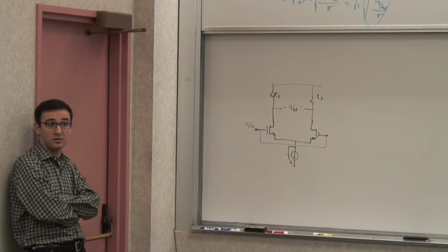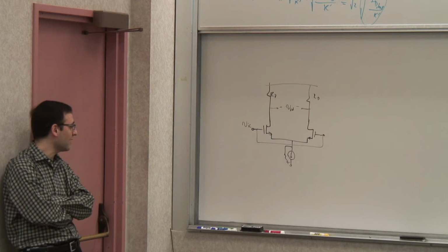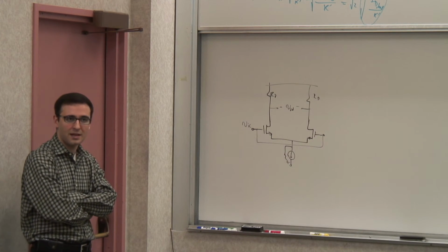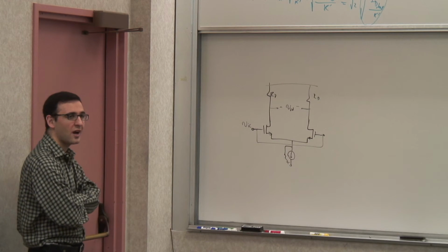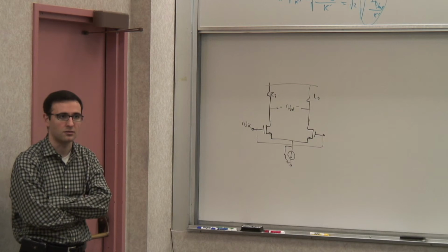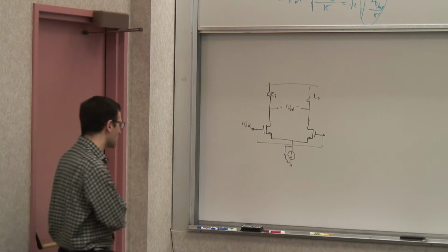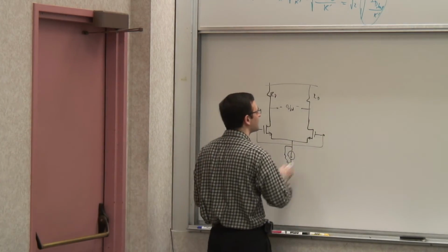Yeah, it's symmetrical as is, so for as long as it's symmetrical, there would be no conversion from common mode to differential. But to maintain this exactly symmetrical, you have to make these two sides identical in values. But you can never make two resistors or two transistors that are identical. You can try to make them closely matched, but they are never identical. So there's always a difference.